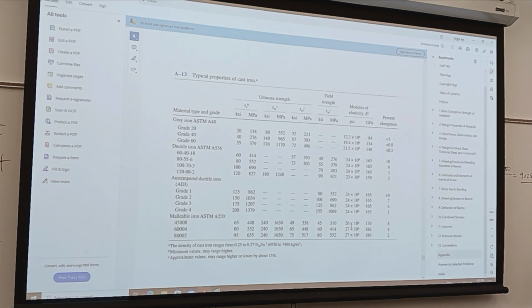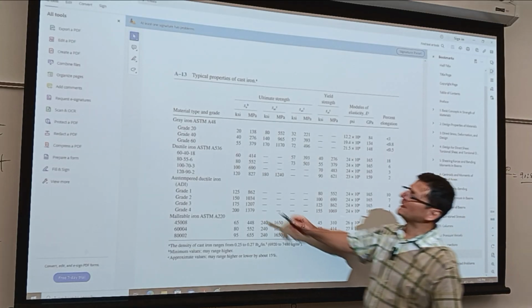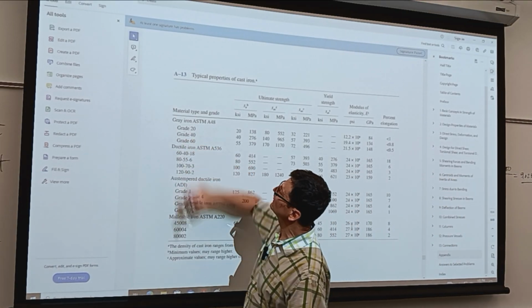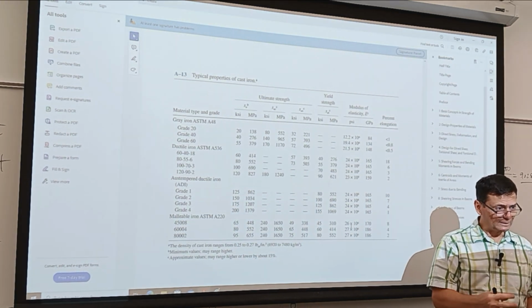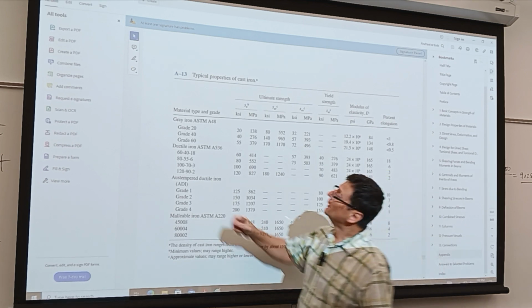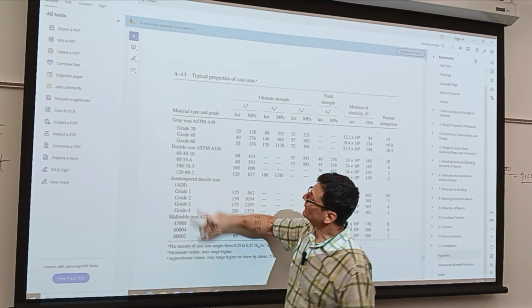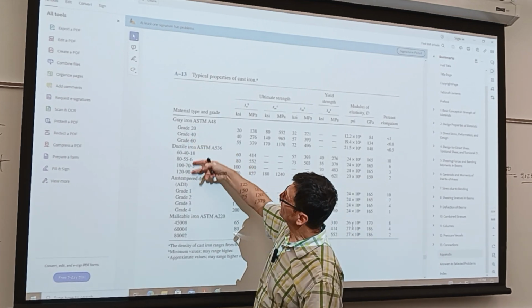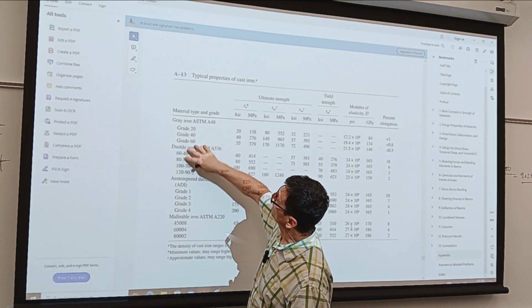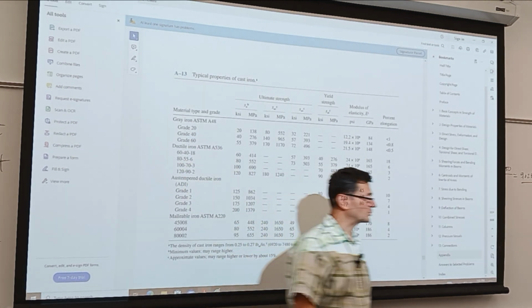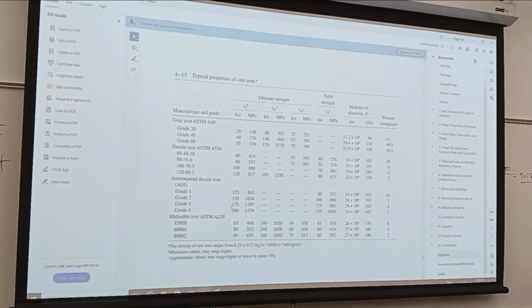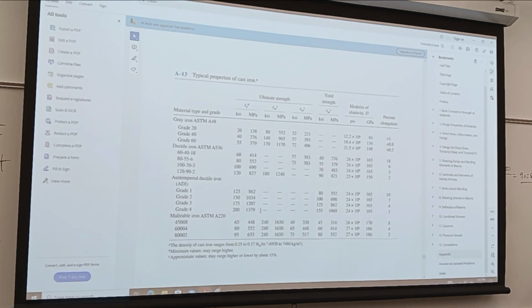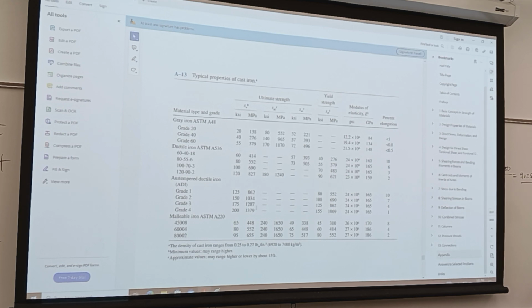versus those made of steel. They cast well. The thing is, they melt at a lower point than carbon steel, and it's fluid, so it casts very well. You can get intricate parts out of iron, okay? But the graphite in them, depending on the way it's formed, the way it precipitates, the graphite and the percentage of carbon dictates or conditions the mechanical properties.